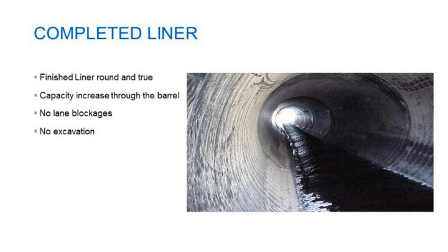So you have a completed liner. Once the grouting is completed, you have a rehabilitated culvert that has extended the life of this host culvert for many years. We've done this without excavation, with minimal traffic disruption, if any at all, and with a great cost savings when compared to dig and replace. Most culvert rehabilitation projects are generally on average 30 to 50% less than a dig and replace process.